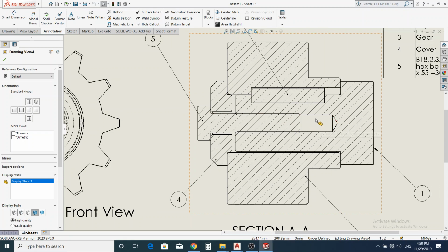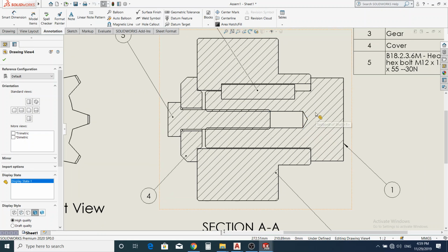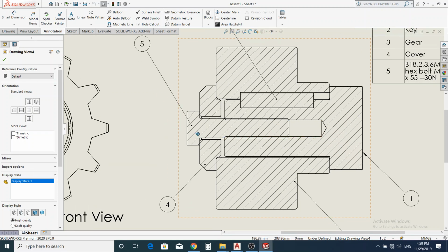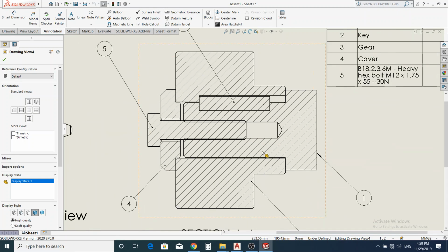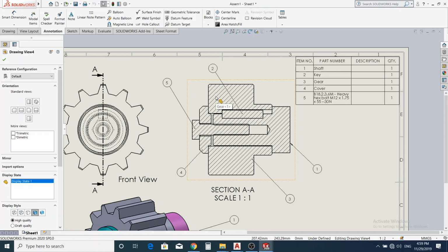So I made a pre-drilled hole in this shaft, and then I tapped it, and by means of this M12 screw, I have been able to restrict the movement of this spare gear in this direction.